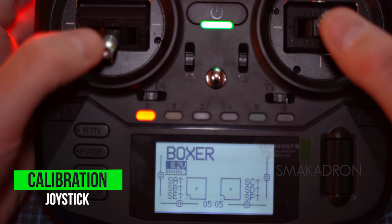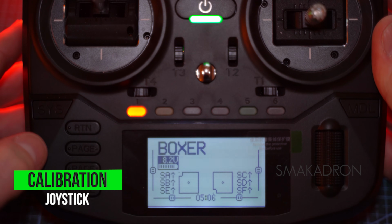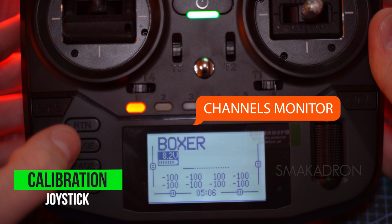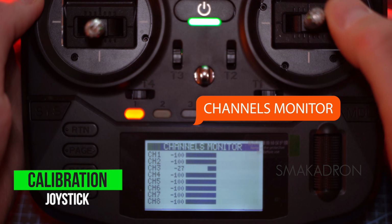After updating the firmware, it's important to note that the sticks on the radio must be recalibrated. To check how well the radio transmitter is calibrated, you need to go to the initial screen of the radio. Then, using the Page key, navigate to the channel's monitor menu. Here, we can see how our sticks are calibrated.